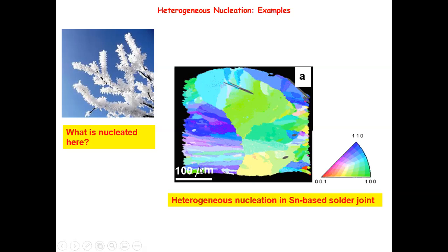Okay, so one thing you can clearly see is that this is a two-dimensional EBSD slice of the crystal structure. Sometimes we call this the color map for the crystal orientation, or crystallographic orientation image. So each color of this region represents a particular orientation with respect to some reference system.